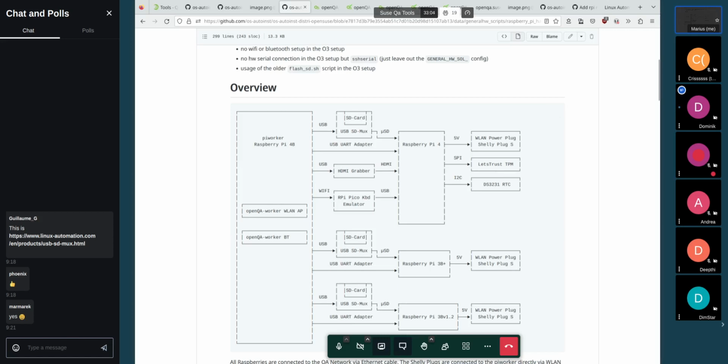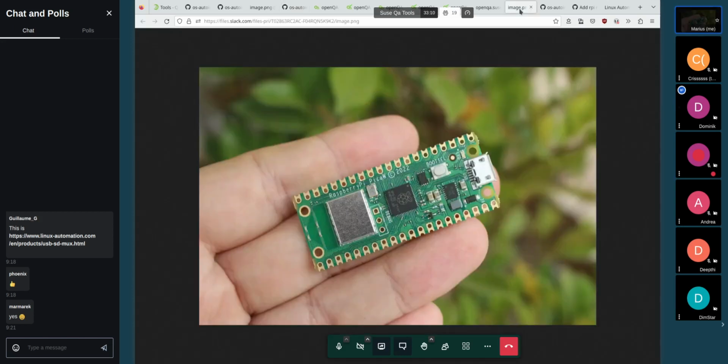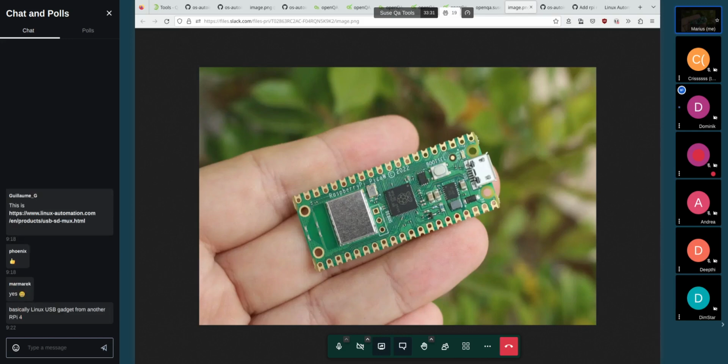What I'm using now is a Raspberry Pi Pico microcontroller. I can show you the image of one. It's essentially like an ESP32. I'm using the Wi-Fi equipped version of the Raspberry Pi Pico. And the special thing about this microcontroller is, other than an ESP32, which only has a UART bridge chip, this thing does the USB on the main SoC.